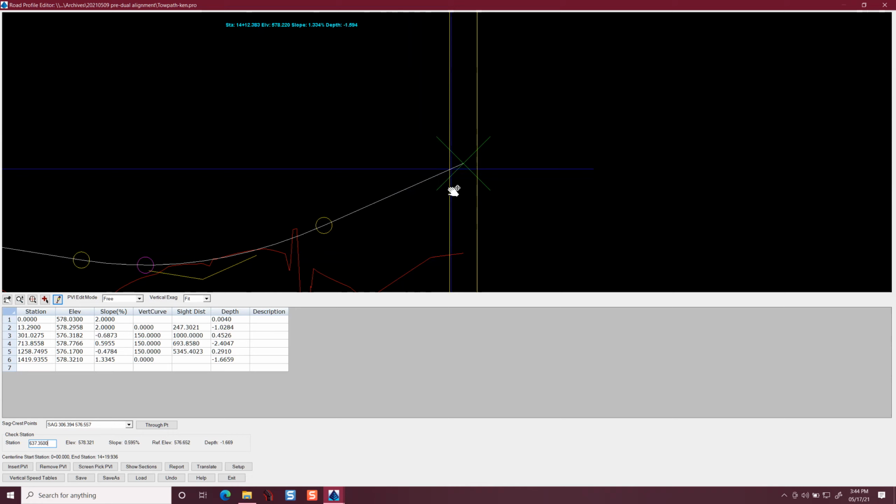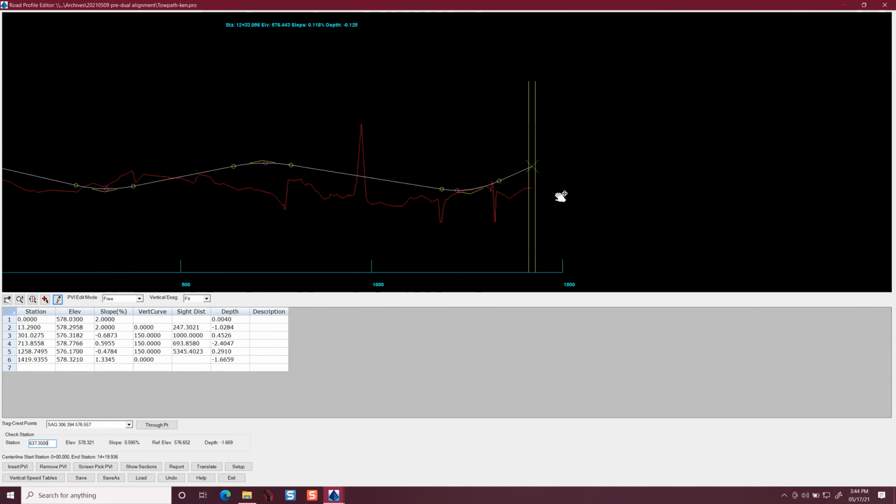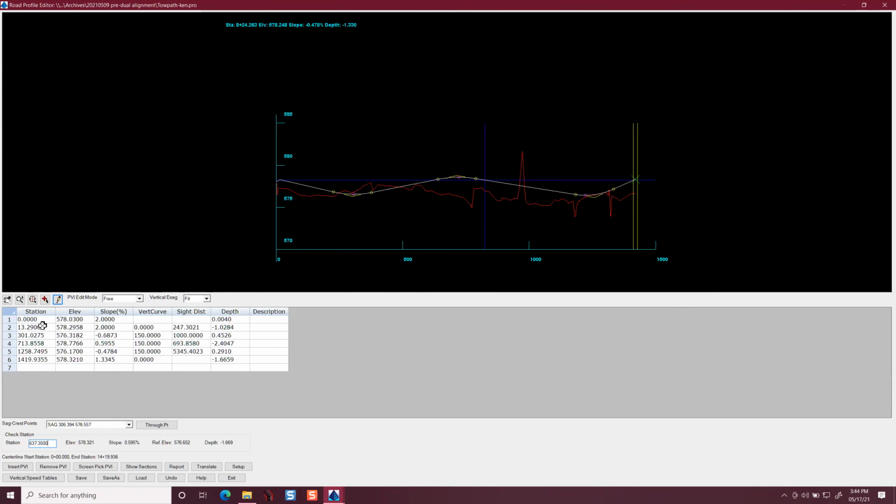So every time you have what we would normally think of as just a single PVI, you'd sometimes get three or even seven. You have two up on the side, two on the far outside, one to get to the edge of pavement, and one across the crown at the center line. It's a zero length vertical curve, but it's still a PVI, so it still counts as a vertical curve.